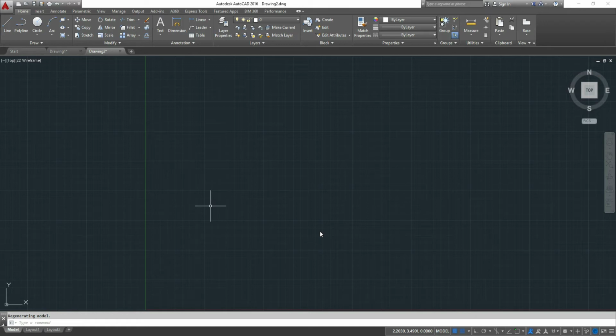To start drawing, the shortcut command for a line is L. So L, enter. I already enabled my snaps on the drafting dialog box. And if my snaps are enabled, they're always available. The grid toggles here, and the snap on and off is here.